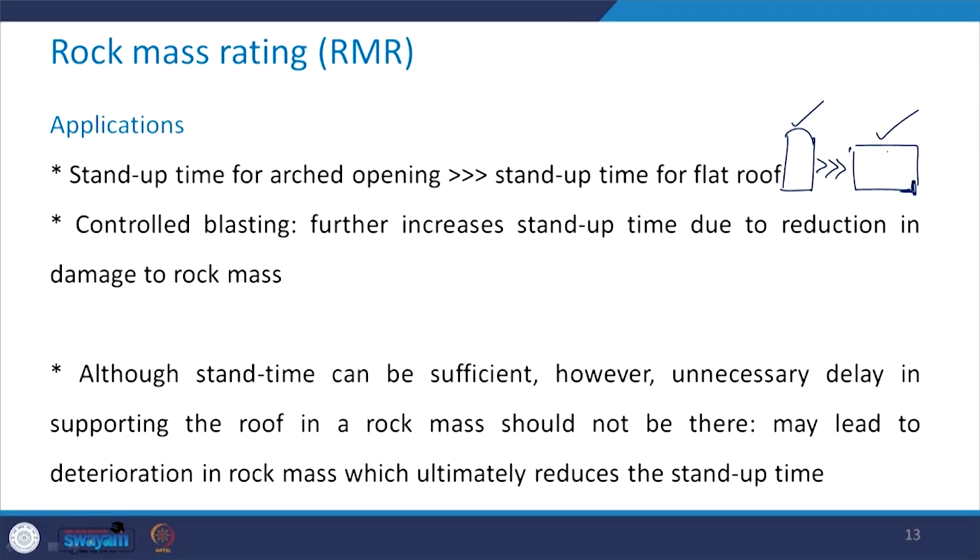Although you have sufficient stand up time, unnecessarily we should not wait till the end of that time in order to provide the support system in the rock mass. Because although the rock mass can withstand up to that much stand up time, wherever there is a free surface, stress release occurs and there will always be deterioration in the rock mass, which will ultimately reduce the stand up time.